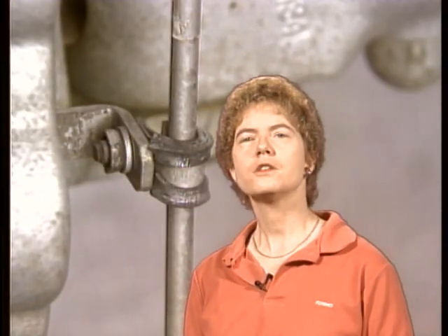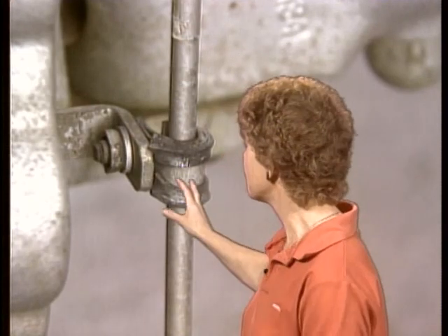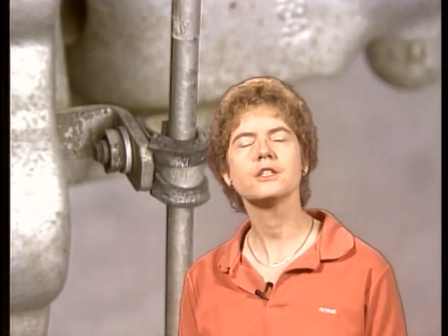Now, let's assume that you're going to be supporting metal tubing. When you're installing metal tubing, you want to use bonded clamps, and when you put on those bonded clamps, you want to remove the paint or anodizing from the tube at the clamp location. The purpose of using bonded clamps, particularly with fuel lines, but also hydraulic and oil lines, the idea is to bond it to the structure so that you don't have any problems.